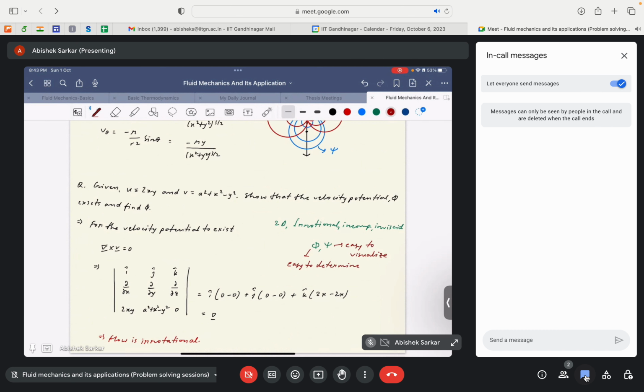And again, for the steady flow case, the streamlines, the streak lines and the path lines are the same. So if the flow is steady, then streamlines itself help in determining the direction of the flow field, because it is equivalent to the path line or the streak line. And we also learned that the density of the streamlines helps us in determining the magnitude of the velocity. If the streamlines are very dense in a particular region, we can tell that the velocity is high in those regions, and if the streamlines are far apart, not that dense, you can tell that the velocity is low at those regions.